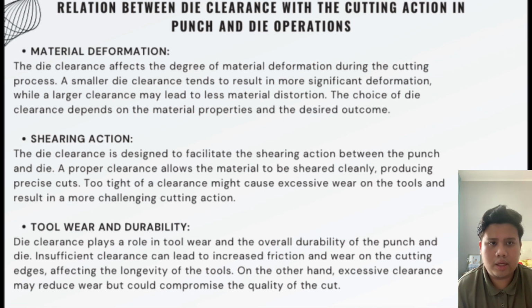Shearing action. The die clearance is designed to facilitate the shearing action between the punch and die. A proper clearance allows the material to be sheared cleanly, producing precise cuts. Too tight a clearance might cause excessive wear on the tools and result in a more challenging cutting action. Tool wear and durability.